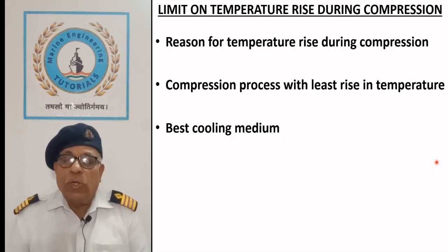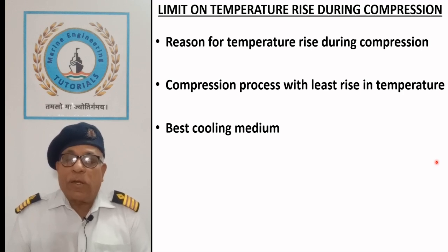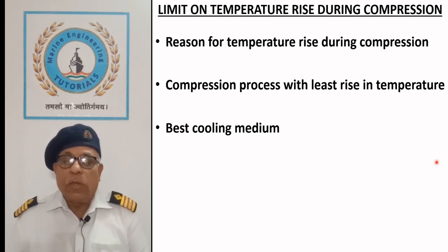Seawater was used for cooling in earlier compressors, which has been replaced with freshwater cooling. Seawater caused frequent fouling of the system and was also responsible for corrosion, which required more maintenance. On the other hand, freshwater avoids all the above troubles provided the water is treated and maintained in alkaline condition.